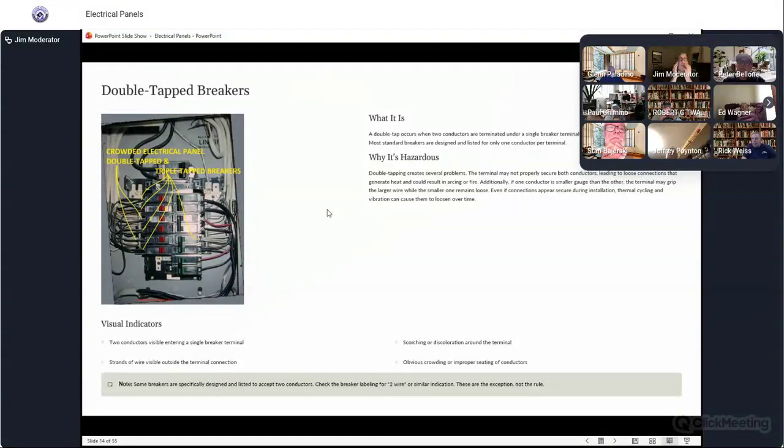A lot of times when you're inspecting, you're going to have an agent there. And I've run into this numerous times: the doorbell is 95% an American Home Pro double tap, the little transformer for the doorbell. And you'll call it out, and the agent will look to your client and go, that's not a big deal. There are always double taps for the doorbell. And I've been doing it a while, and the client will look at me for reassurance, and I'll say, well, we're going to put it in the report, and you're going to have it looked at by an electrician because your agent's not an electrician.